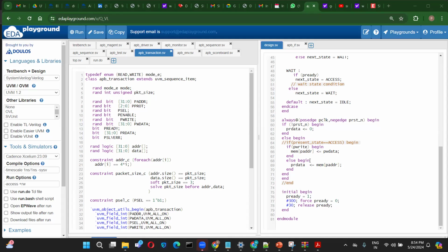If it is incremental, address based, or increments, like if we have an increment of 4, it will do plus 1, plus 2, like that. Based on whatever, if it is an increment, till where it has to go, it will have the data width or something, right? Based on that parameter also, it has to monitor it, and based on that, till where it has to increment. All such logic you have to include in the slave. So based on which protocol you take, the slave intelligence, how it will behave, based on that your design will be there.